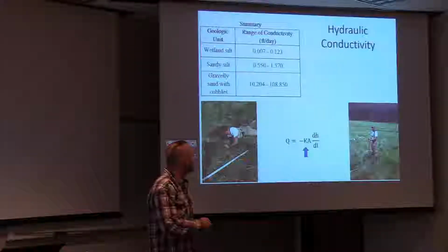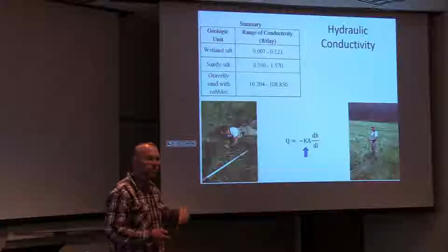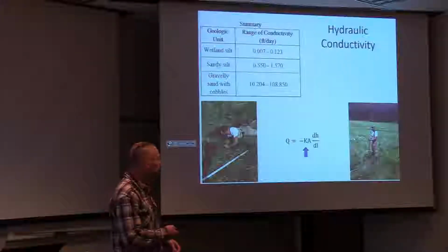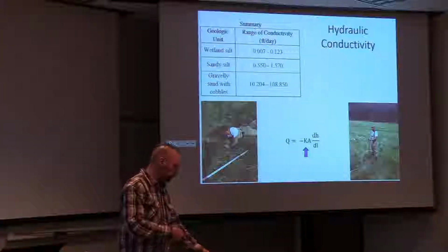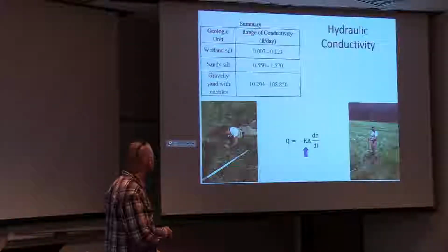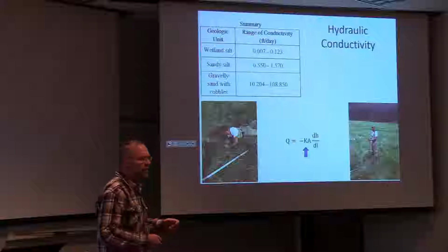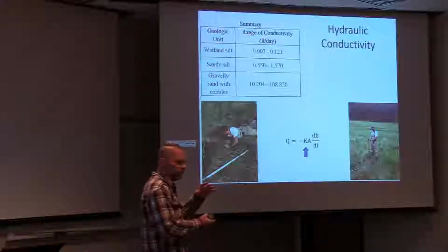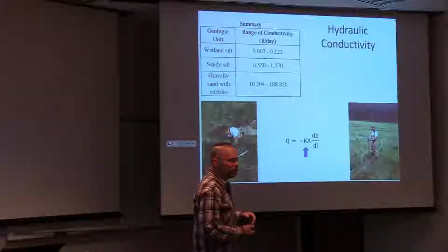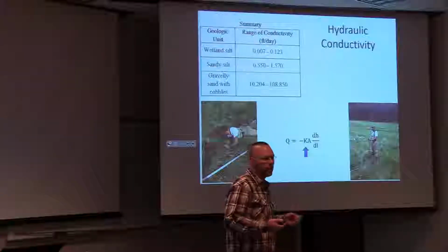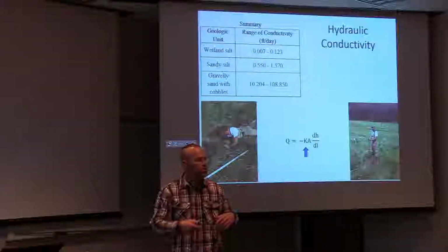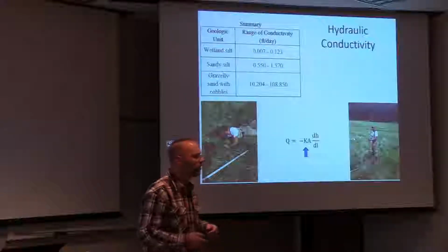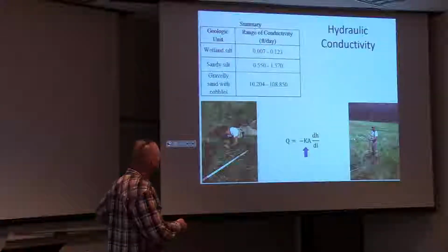And since those wells might be reflecting more of the silt that they're placed in, John took samples of the gravel. He dug down to the gravels and sieve tested the gravel aquifer material, and using something called Hazen's Law, I think is what they use, you can take the distribution of sediment and make a calculation of what the hydraulic conductivity would be.